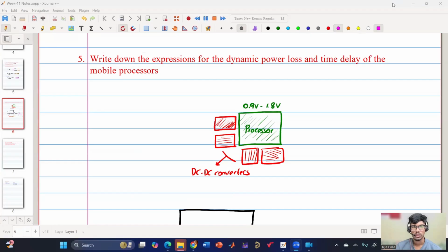Clear, sir, clear. So sir has mentioned the dynamic voltage scaling. So the term itself says that the voltage is being scaled dynamically. So on the go, voltage is changing. It need not be during load transient. Sometimes there can be reference transient as well. So say the load is at the same condition, but voltage now has to change from 1.2 volt to 1.8 volt. So that is called dynamic voltage scaling.